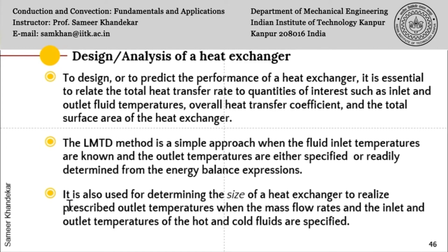Then it is also used for determining the size of the heat exchanger. That is what I am saying, sizing, to realize the prescribed outlet temperature. So for example, if you know the inlet temperatures and for a given size of heat exchanger, the outlet can be predicted. But if that doesn't satisfy the client, then you need to increase the area so that there is more residence time inside the heat exchanger, and so you will get the desired outlet of either the hot fluid becoming colder or the cold fluid becoming hotter, whatever is the main objective function. You achieve that by the sizing problem. So this is how you will proceed.